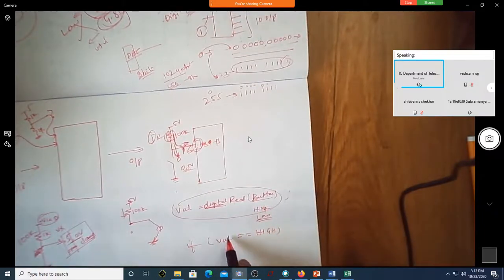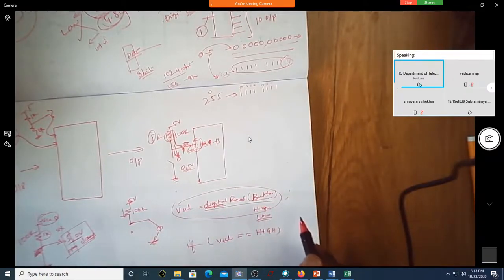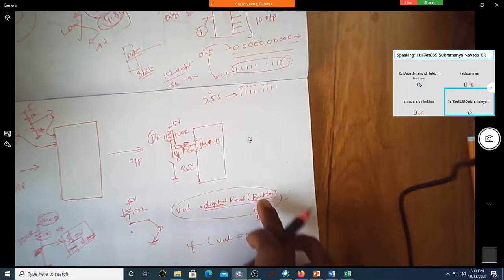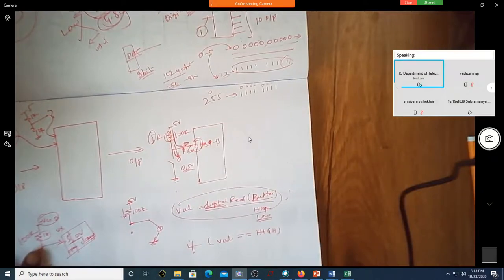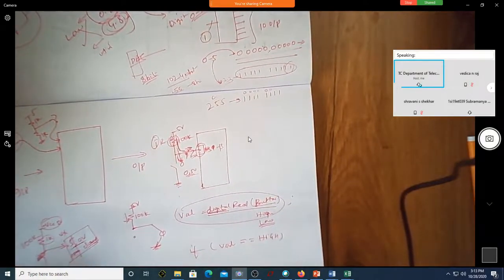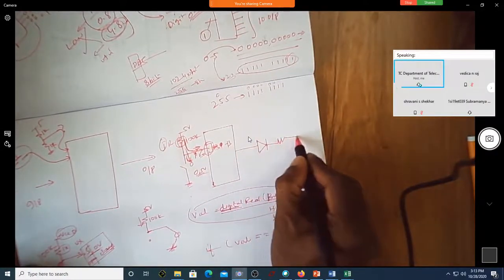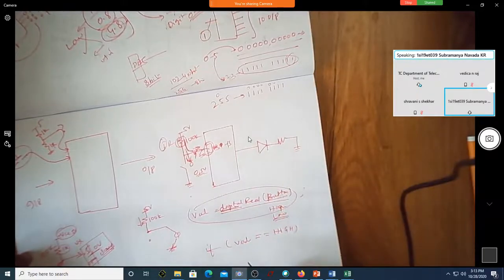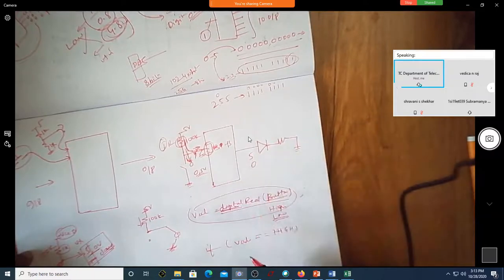Are you not checking the value of val that was read by this statement? So you are digitally reading the button value, meaning the button to which this is connected. If it is true, then I have to write something onto the pin. Assume that you have an LED connected here. So this LED will be on if it is 5 volt, it will be off if it is 0 volt.